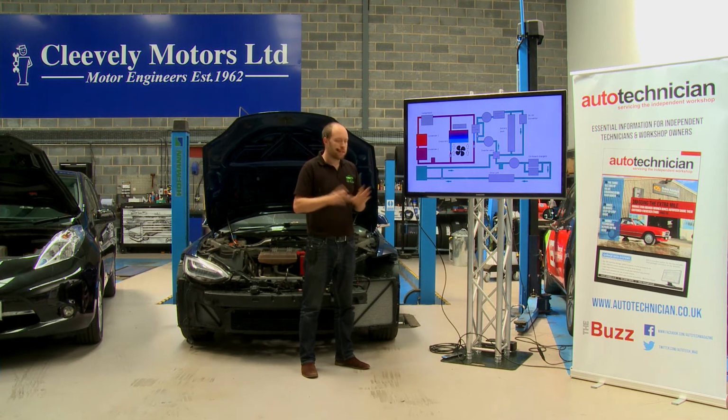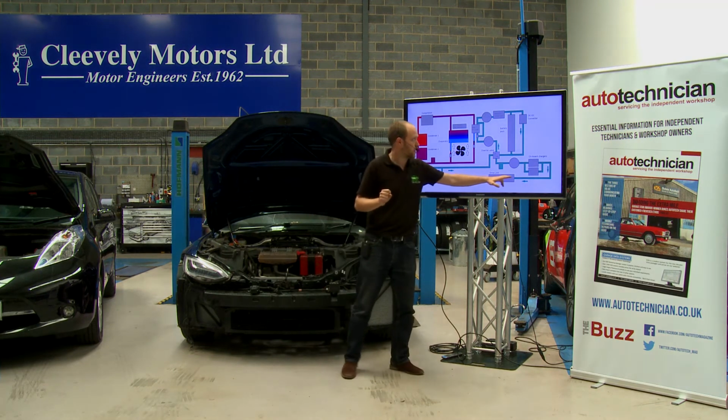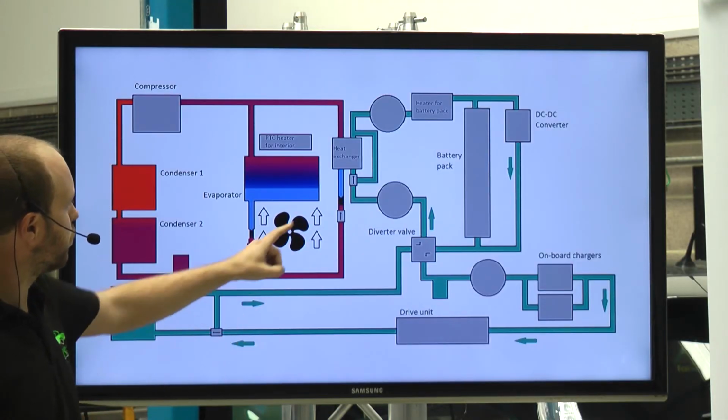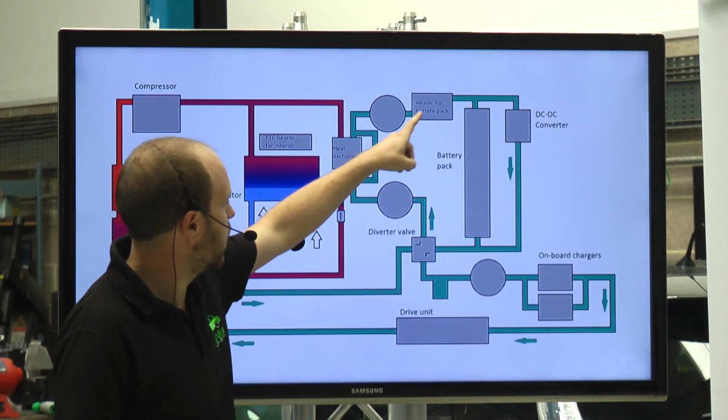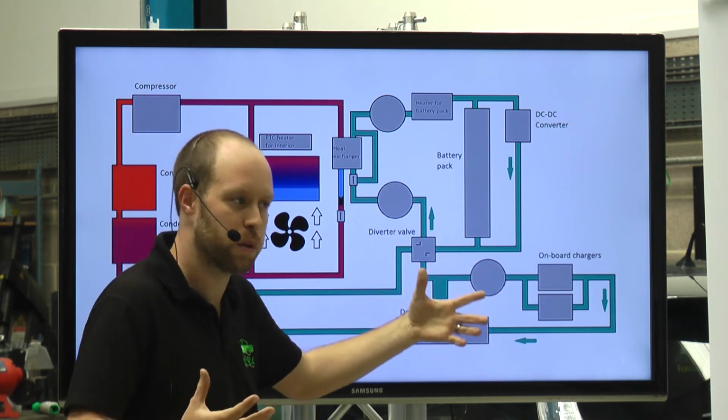So there's one situation where we might want to cool the drive units and at the same time heat the battery pack. And that seems very wasteful. If we turn this heater on, we're then going to be heating up this part of the circuit, and we're then inadvertently going to be heating up our electronics, which we don't want to do.